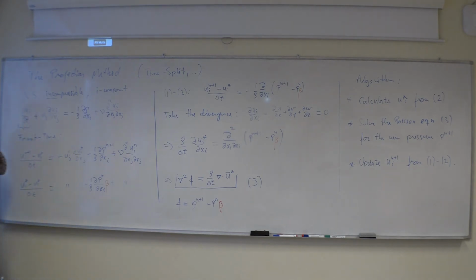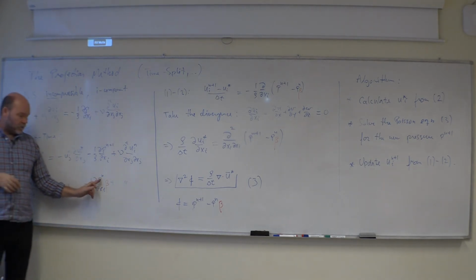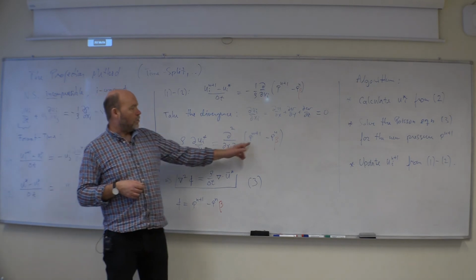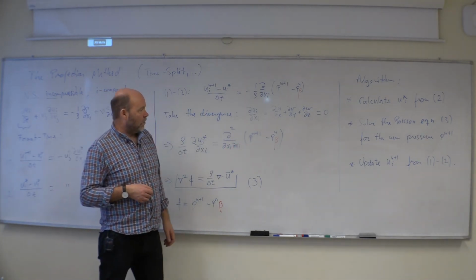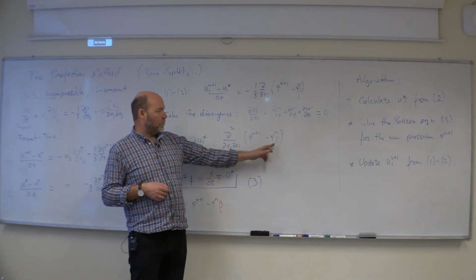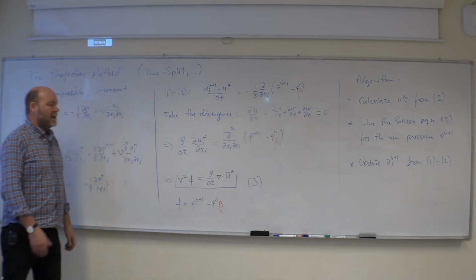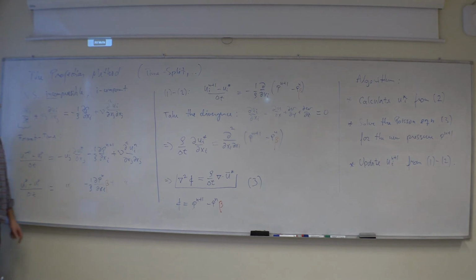So you might also say that the previous pressure field is a very good initial guess for the new pressure field. So it's faster to use beta equals 1. So just forget about this beta parameter. You could use beta equal to 0 if you wanted, but it doesn't help. It doesn't speed up.